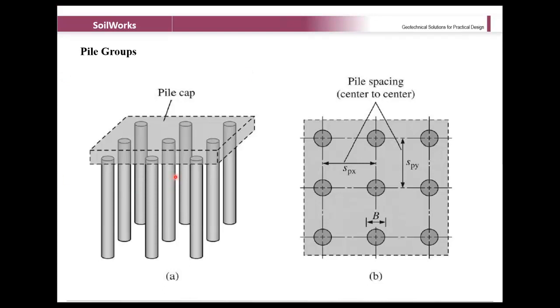So basically, in the case of a pile group, the lateral load distribution is not similar to that of a single pile. Hence, this provision of springs does not serve the purpose. Whenever you go for linear spring calculation, it does not serve the purpose for a pile group, because those equations are derived for a single pile and we have a pile group.